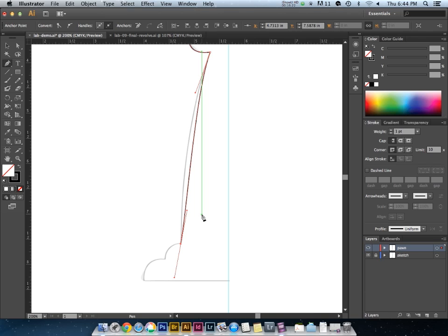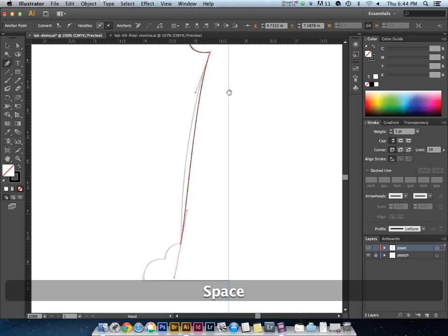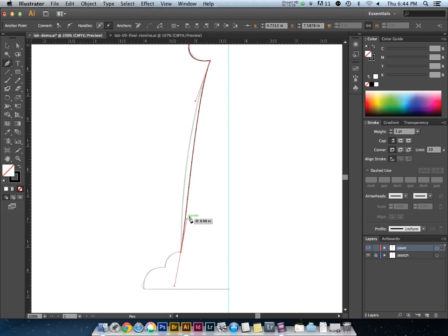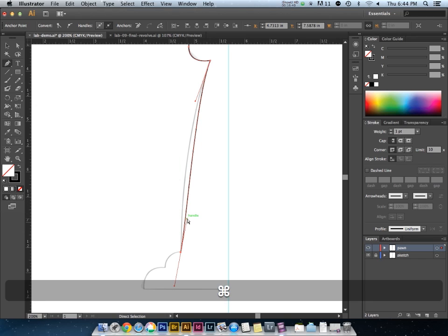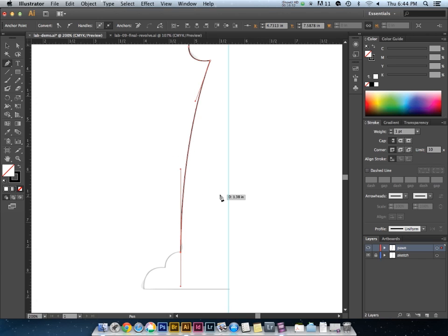But for now, why don't you go ahead and click on the direct selection tool, and then click on that point and move it down to that corner. And then we'll go ahead and make the adjustment from there. So you can see that I don't quite have the curve following that line very closely. It's a little flat. And all I need to do is move the handle by clicking on one of the control points for the handle and simply slide this upward to adjust that curve so that it's pretty close to my original line.